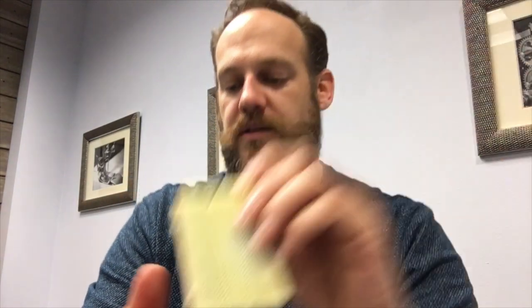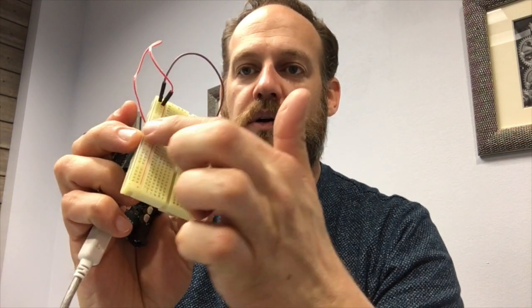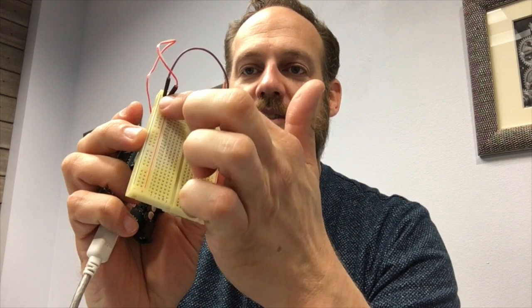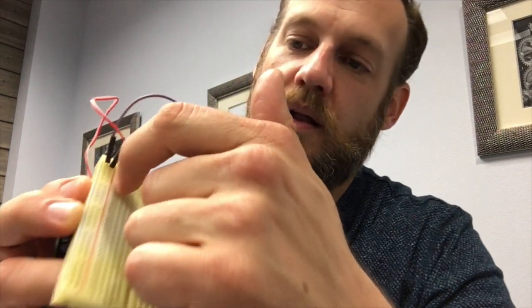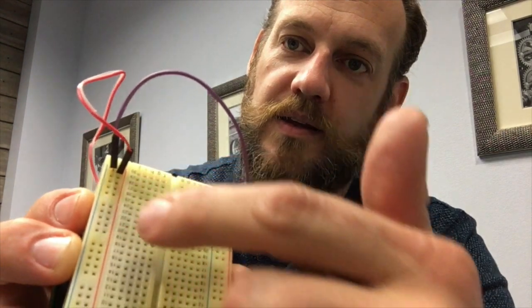There we go, now we can see. Excellent, so let's put the purple into the negative on the breadboard and the red into the positive. Now, what that does is runs power from the Arduino all the way through this strip. Now this strip is parallel this way, and these pieces are parallel that way. So we're going to have to run positive from the red wire on this side into here and negative into here. To do that, I'm going to use